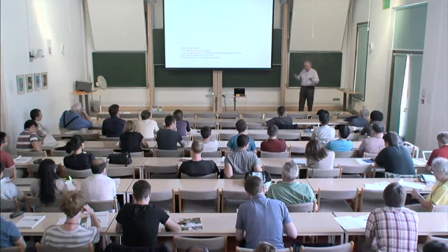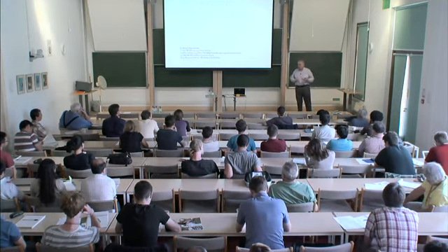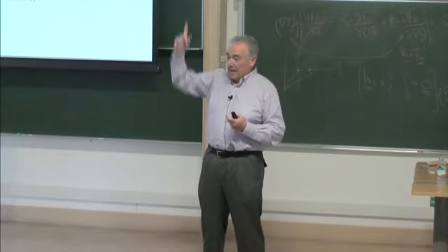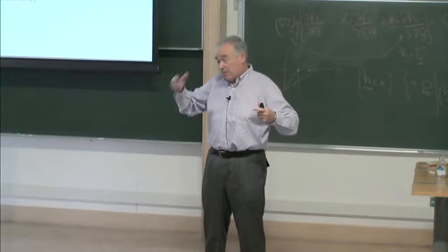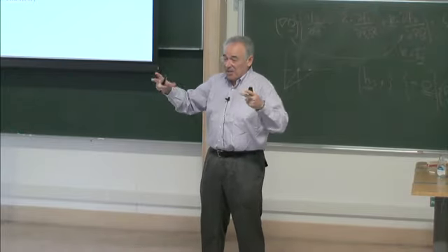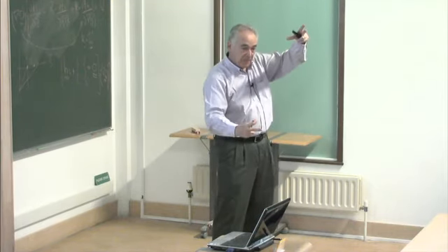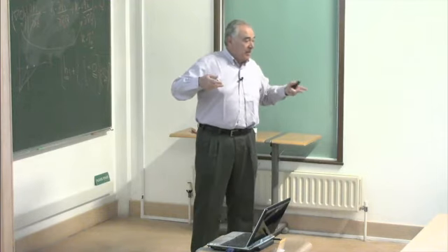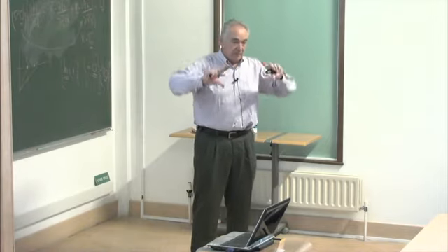So if you want to do capillarity in anisotropic systems, you have to equip the surface with a vectorial interfacial tension. The normal component describes size effects, and the tangential component of that vector describes the tilting. So you can change the energy by changing the surface area or changing the surface tilting. And that gives rise to a new capillary pressure called the Herring capillary pressure that takes into account tilting.